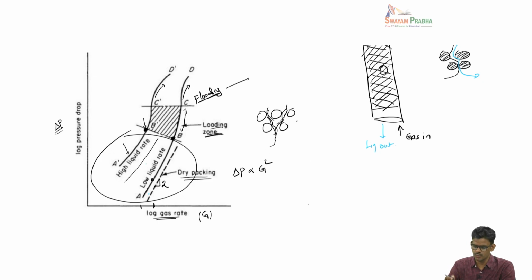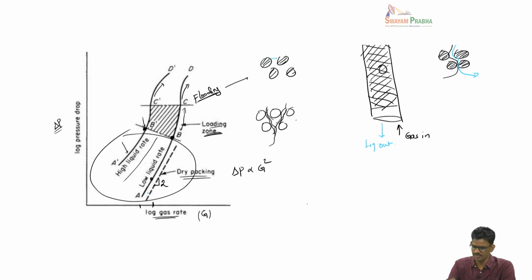When you go to the flooding situation, the entire pore will be filled with liquids, okay. All these pores will be filled with the liquid film, and the incoming gas will have to bubble through. It will go as bubbles. Do you follow the loading and the flooding?